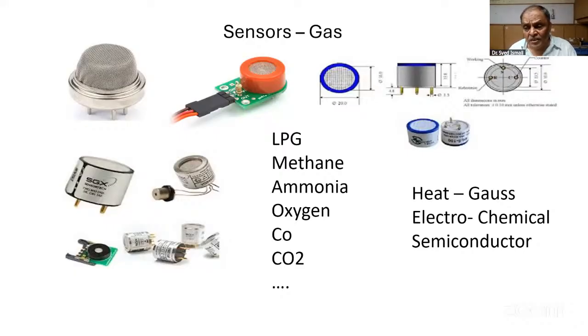One more important thing with gas sensors is calibration. They go off very quickly. Some of them, like CO2 sensors, you have to calibrate every 15 days. Otherwise, the calibration goes off. So you have to be careful and read about it before blaming the supplier or the technology.